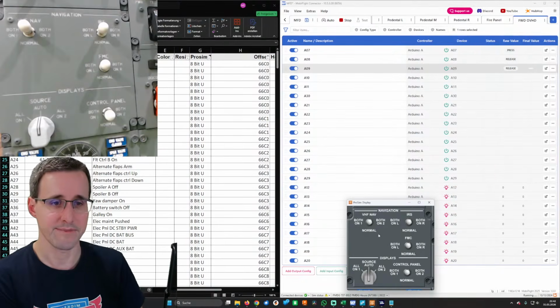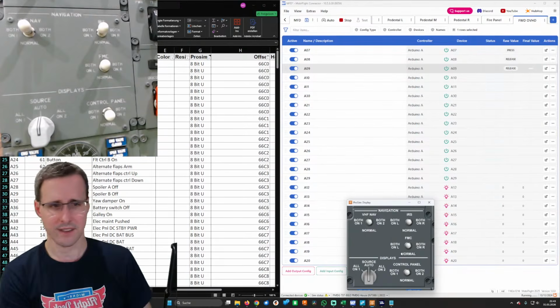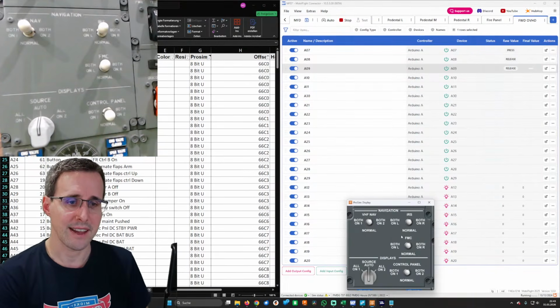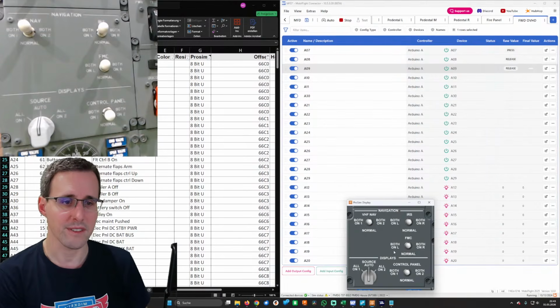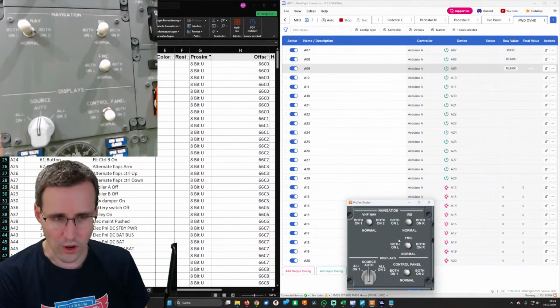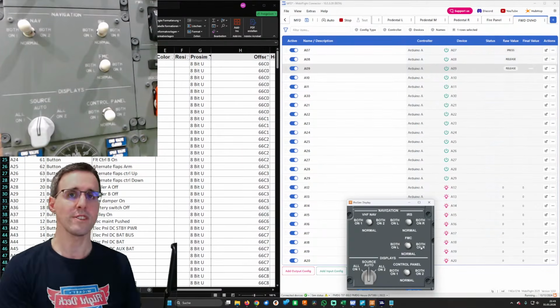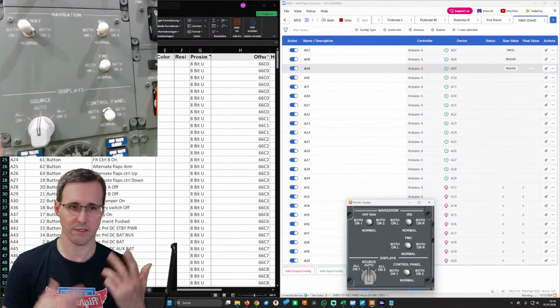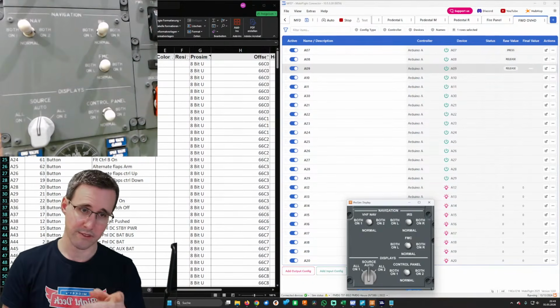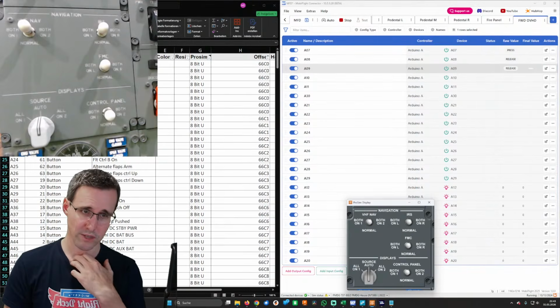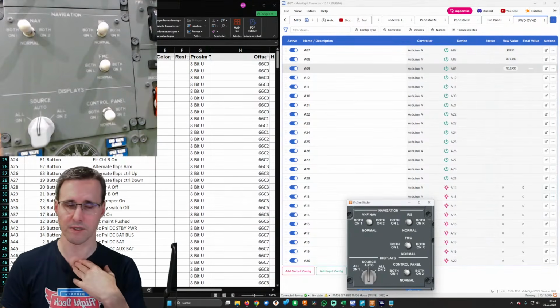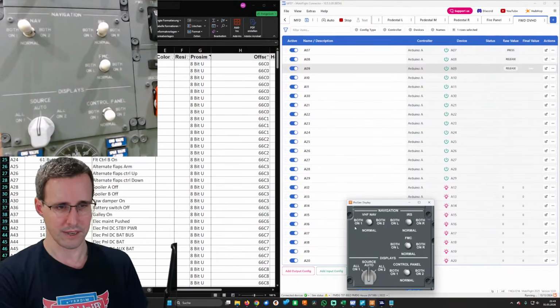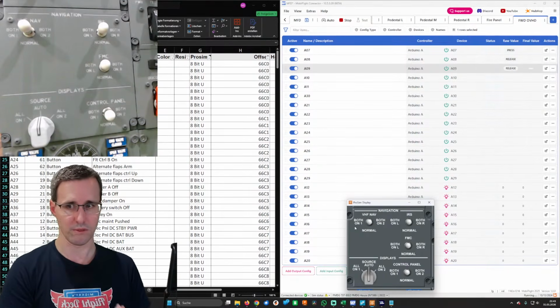When we have, like in the panel before, a three-way switch, no? These are 3-way switches, and I have always connected only 2 of them, no? It is an on-off-on switch, and only the 2 on sections are connected with a cable here. And yeah, maybe this is the problem, but we will see. When we now have the same problem here at all the switches again, then I have to rethink the cabling. But I don't hope that this will be a problem here.